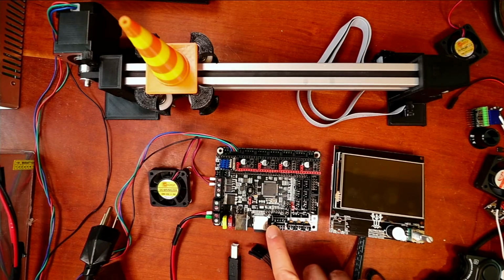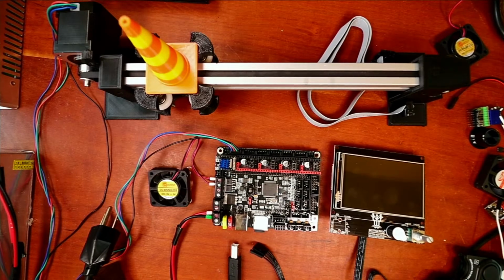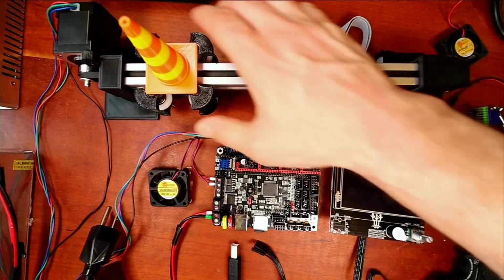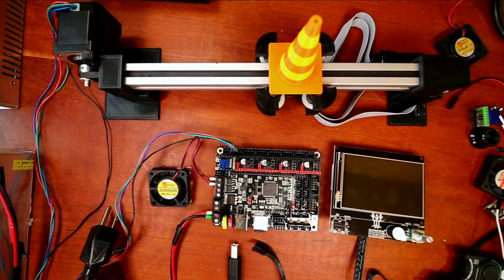You can connect to each one of these pins with a particular device that connects via USB, and you can watch the pulses in microseconds moving up and down. It's a great way to troubleshoot if there's a combination of things going on. Unfortunately, I don't have one at my fingertips at the moment to show you. Usually they're big boxes. But an O-scope would be another way to do it. Or even a multimeter if you can see it move quickly. But the O-scope has the ability to set triggers. You can actually see the rise and fall of voltage.